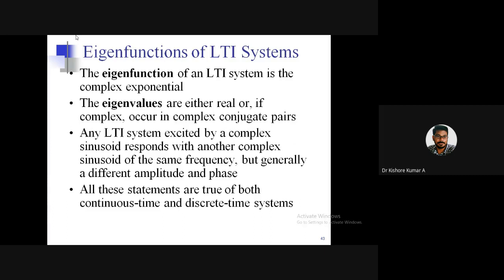So now we can have the eigenfunctions of LTI systems. The eigenfunction of any linear time invariant system is the complex exponential. Either it may be real or complex, and it occurs in complex conjugate pairs. LTI systems can be excited by a complex sinusoid and respond with another complex sinusoid of the same frequency, but in general with a different amplitude and phase. All these statements are true for both continuous time and discrete time systems.